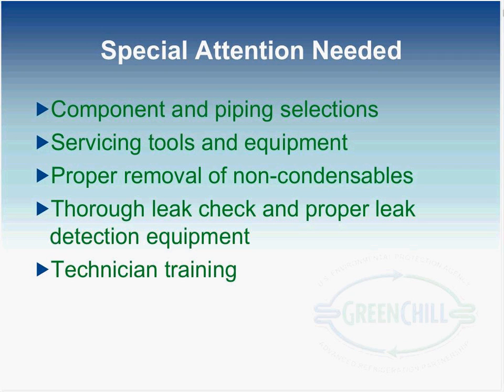Also, the use of CO2 in a direct expansion cycle with the use of electronic expansion valves. There are currently no thermal expansion devices that we're aware of in use and approved today for a cascade system. But also consider the cascade heat exchangers when you have multiple heat exchangers used in parallel.